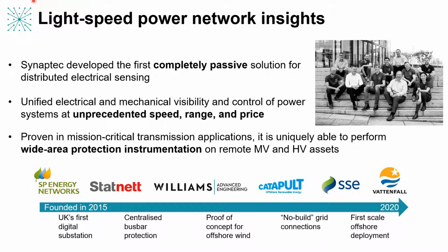And we use that fiber not as a telecoms medium, but as a means of transmitting analog measurements of electrical parameters. Now, the ability to measure electrical parameters passively over long distances and at multiple locations is unique to Synaptec, and it allows us to provide high quality point-on-wave measurements of current and voltage at unprecedented speed, range, and price when compared to alternative or traditional measurement technologies. And this means that it's particularly well suited to providing simplified protection instrumentation for complex circuits.